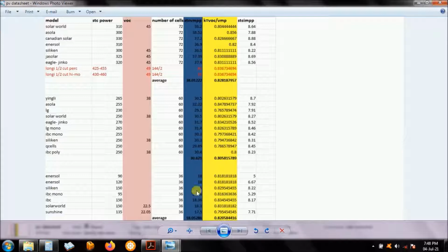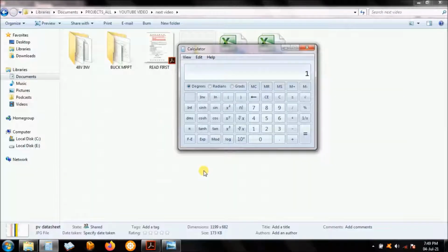So what we do is we look at the constant voltage. The constant voltage for the maximum power, 100 watt solar module divided by 18 volts, that will give you 5.5 amps. Right, you connect this module to a battery, a 12-volt battery. We know a 12-volt battery gets up to 14.5, 14.9, depending on the manufacturer recommendation. We are going to use 5.5 amps charging that battery.